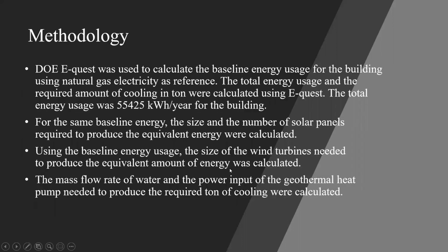So onto our methodology. The first thing we did was calculate the energy used for our baseline system, which is the natural gas electricity system. We did that using the eQuest software to get all the energy used for the year for heating and cooling, and then the amount of cooling and heating required in tons.